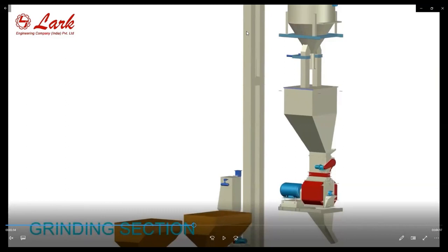So 180 amperes. What the rotary vane feeder will do is, when the amperes of the hammer mill go above 180 amperes, it automatically slows down the feeding through this VFD and the rotary vane feeder. And when the amperes drop below 120 or 130, it automatically increases the RPM to enhance the feeding process. So the rotary vane feeder, with the help of the VFD, helps to control the feeding, the power, and the safety of the motor.